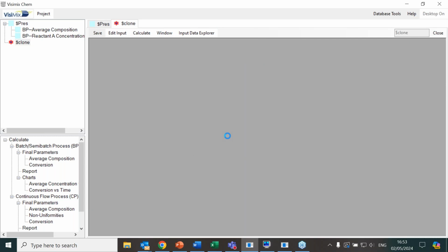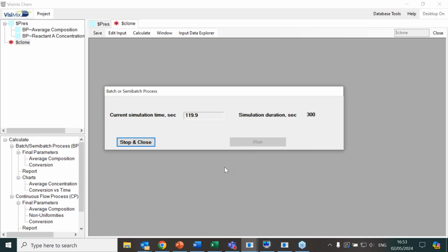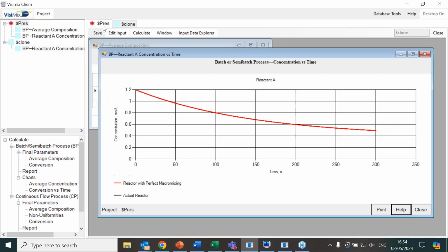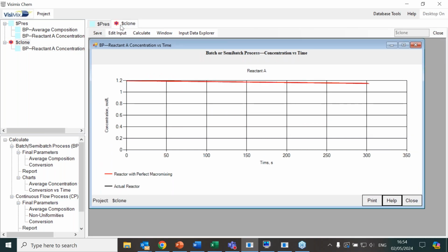the concentration of A, it will, of course, ask me to run. Now you see that it is completely different. Even if we think that it was homogeneous and we will get exactly the same results, you can see completely different results. But it is batch. It takes 5 minutes, but it can take 2 hours, and it is a typical report that we get: I did it in the lab, it takes me 5 hours, and the production takes me 10 hours. Yes, because the diffusivity inside is different.